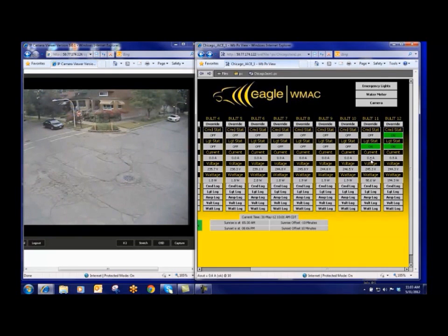You'll see over here, current's dropping. We don't lose status until current is 0. Current is 0, light status is off. Override command, we want to do the same thing for this light. Override off, if you'll watch the lights, we hit OK. Light is off instantaneously. Current will start dropping, and we lose status as soon as we get 0 amperage.